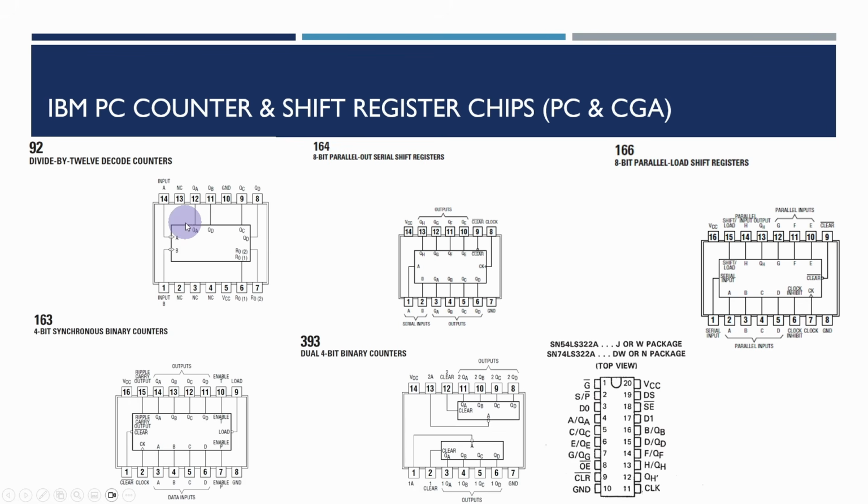And then on the counter side of things, this particular one, the 322, is used for the keyboard controller. That's obsolete. You can't really get those anymore, and the diagrams aren't even in the TI datasheet anymore. And the main recommendation I've seen is you construct one of these from a programmable logic device should you want one. But invariably this has been replaced now by the PS/2 keyboard mouse controller, so not really going to worry about that too much.